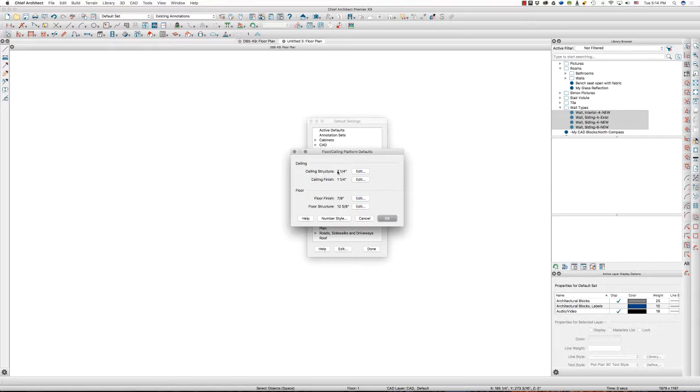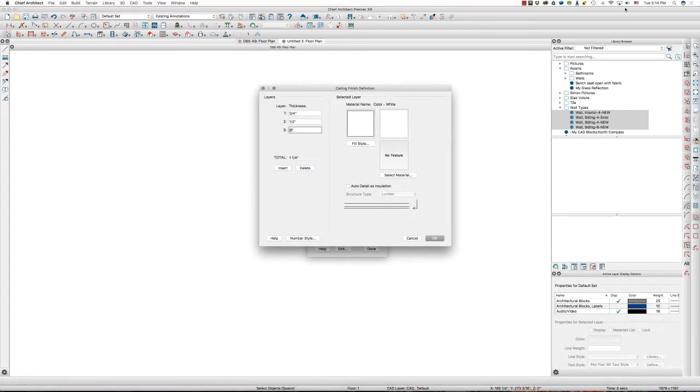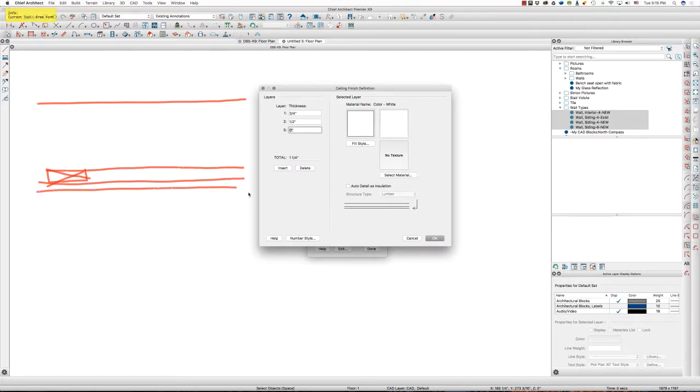In my ceiling structures, I like to use 2x8s. Chief Architect puts it as 2x6s, and we can change this. That's fine, right? A couple of tips. On the East Coast, they use strapping. So if we've got the ceiling joist, they put 1x3 strapping perpendicular to the joists, and then 1/2-inch blue board and plaster.